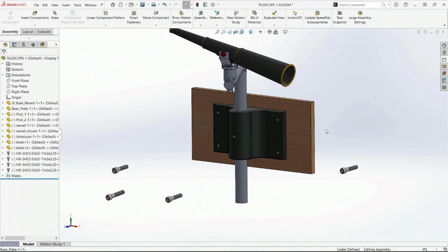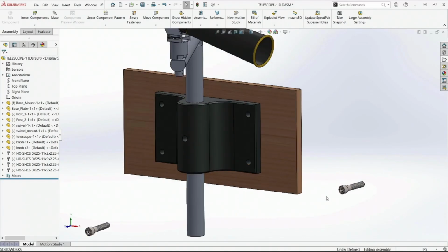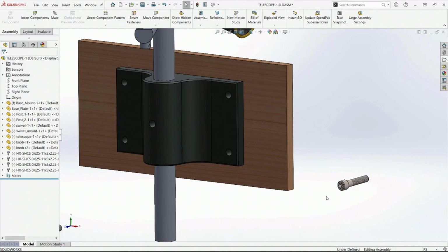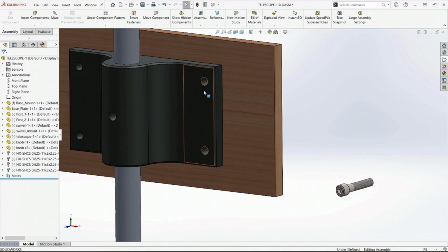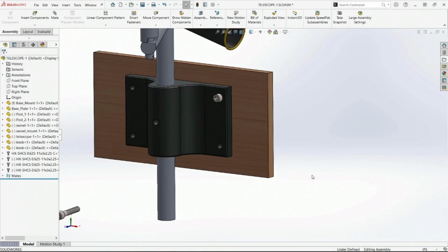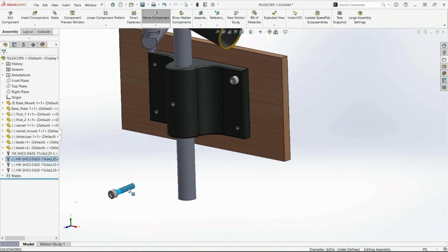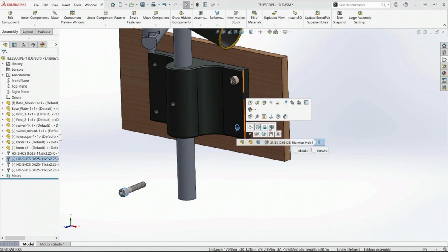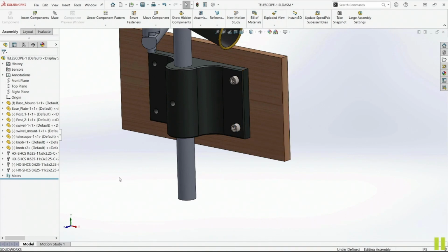All right. Next, you might remember from when we were looking at those profiles, the circular profiles available as well. The profile center mate is also available on the quick mates. So here, I'm going to go in and just control select those 2 circular profiles and apply the profile center mate. We can change that offset distance. We can even lock the rotation there. And we've easily added that profile center mate in there. What's really nice about that is you can fully define a bolt with just one mate: choosing the profile center mate, locking the rotation, and fully defining that bolt there.